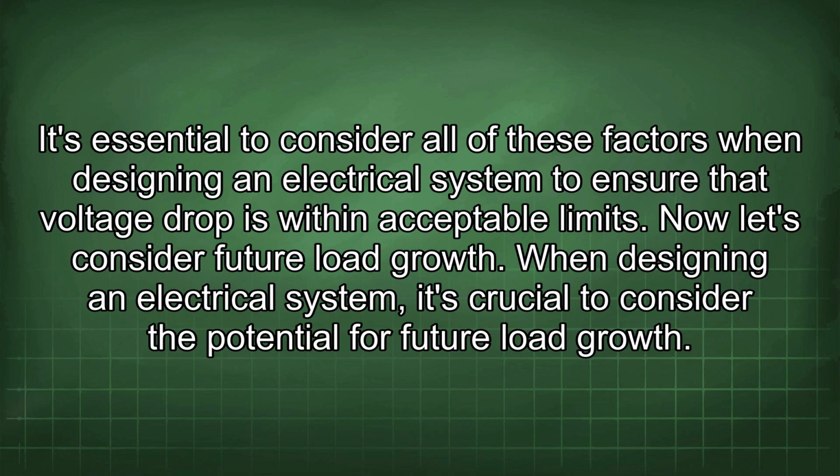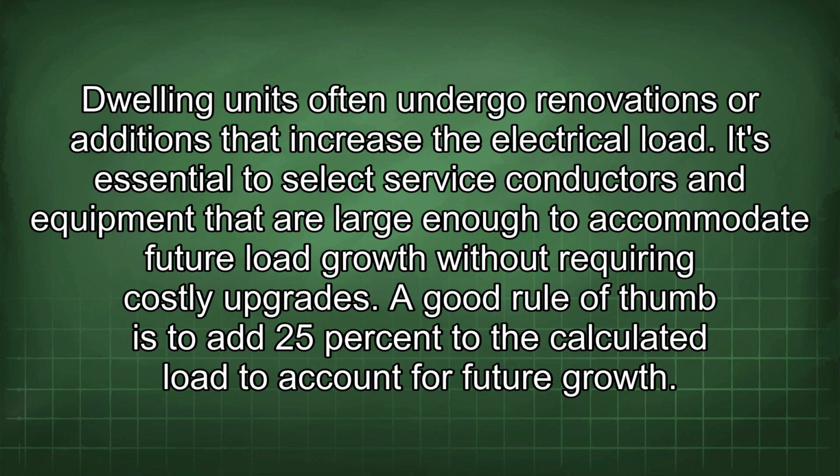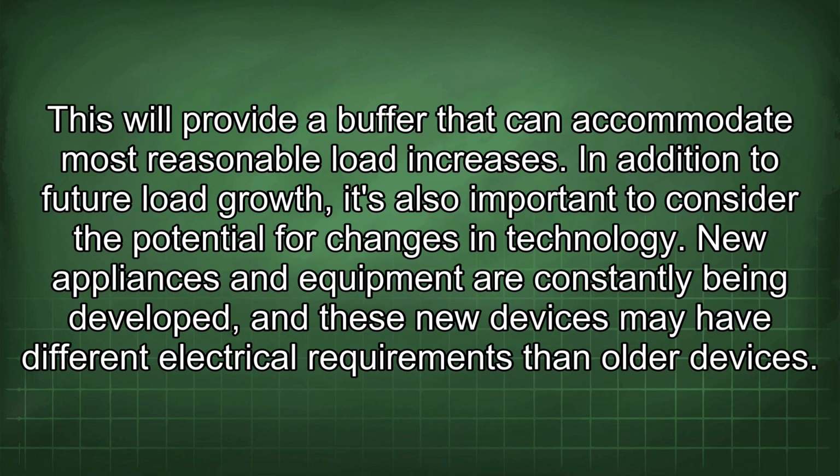When designing an electrical system, it's crucial to consider the potential for future load growth. Dwelling units often undergo renovations or additions that increase the electrical load. It's essential to select service conductors and equipment that are large enough to accommodate future load growth without requiring costly upgrades. A good rule of thumb is to add 25% to the calculated load to account for future growth.